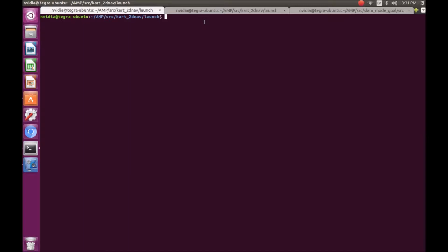So I have a few files here, a cart configuration launch file and a move base launch file. The cart configuration launch file configures the size of the cart and the Velodyne sensor, whereas the move base launch file does a lot of the path planning and the SLAM algorithms that will be run as the Lidar is also being run. To launch each of these files, we'll just use a simple command, ROS launch, and then the actual name of the file. When we launch each file, we want to make sure there are no errors and no warnings, so it looks like we're good here.